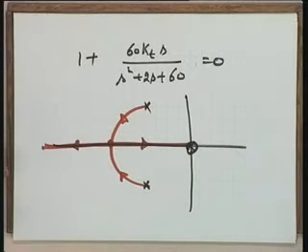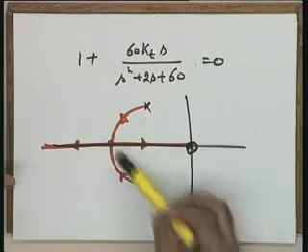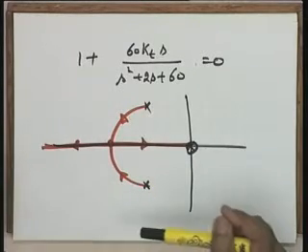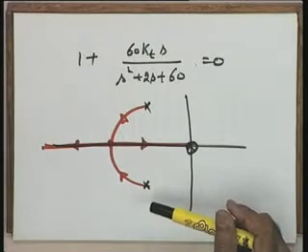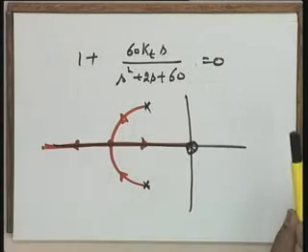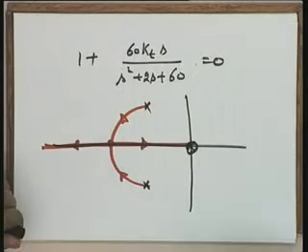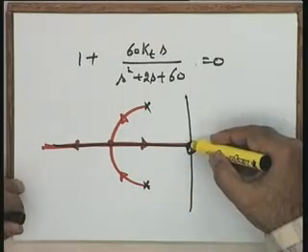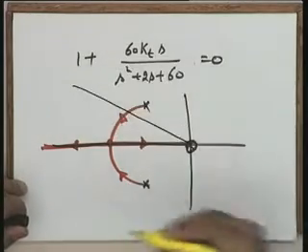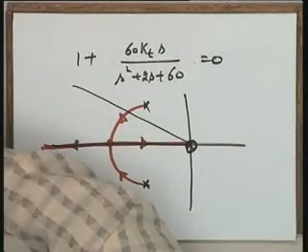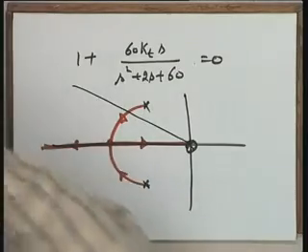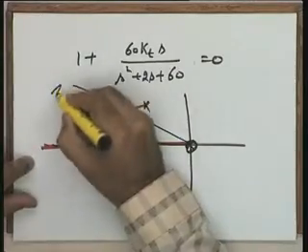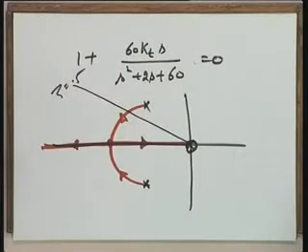A simple exercise for you: prove that in this particular case the complex root locus branches are in fact part of a circle. This I leave to you, but suppose this is drawn in this particular case. What is the next exercise? The next exercise is to draw this particular line at zeta equal to 0.5. Let me see if I have the result. Yes, I have the result available. Zeta equal to 0.5.